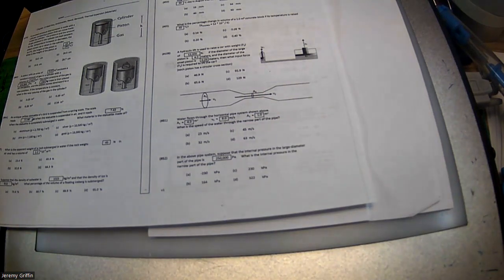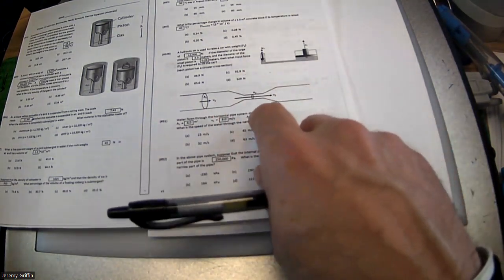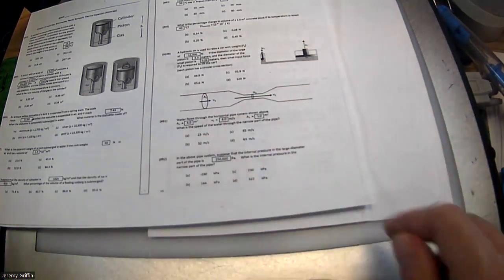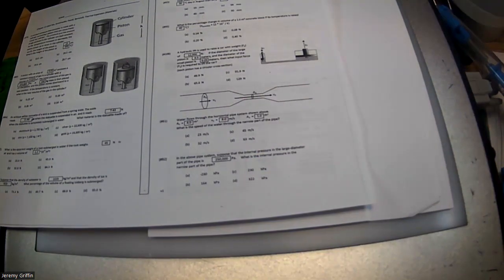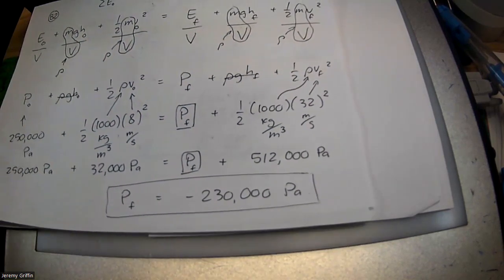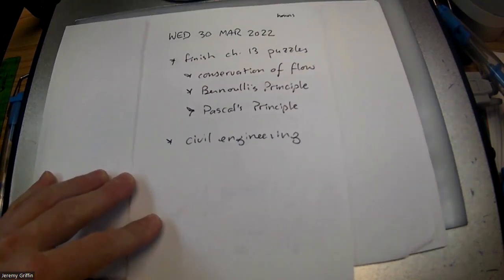If you guys are ever engineering, I should say that happens a lot in pumps. Sometimes that can ruin the pump too, because you have moving parts, fast moving water through narrow spaces, which can cause cavitation bubbles. So if you guys are ever engineering a pipe system one day, this would definitely be something to keep your eye on. Conservation of flow and Bernoulli principle, and make sure that you aren't getting internal pressures that would boil the water in your pipe system. You guys get that?